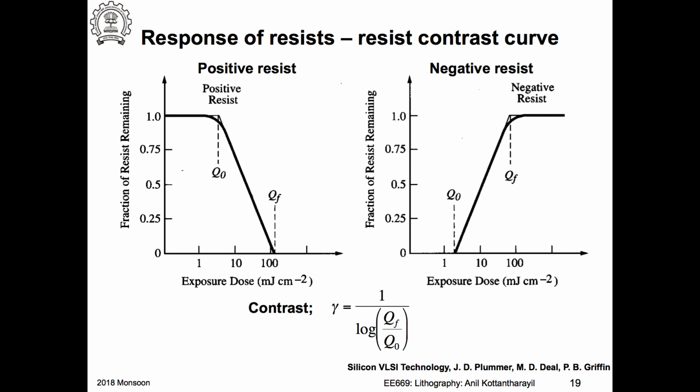So we were discussing yesterday the resist contrast curves, right? And prior to that we had a discussion of the modulation transfer function. So the modulation transfer function essentially is about the optical system and then your mask and the image that is actually incident or is appearing on the image plane. Okay, but then the image has to be transferred to the photoresist.